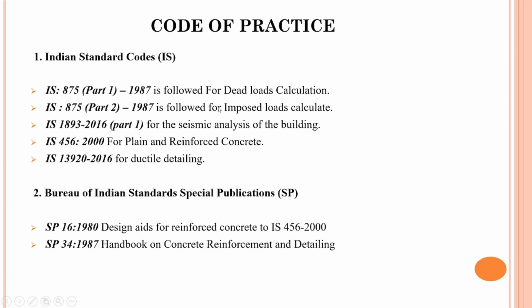In your project, what kind of codes you have practiced for solving or using in the software to calculate and complete the project. Here I'm including the Indian standard, but you have to use your own code or a different code. You have different codes, whatever kind of code you have practiced, like IS 875 part 1 1987 for dead load, part 2 for live load, like this. You include what kind of code you have practiced.